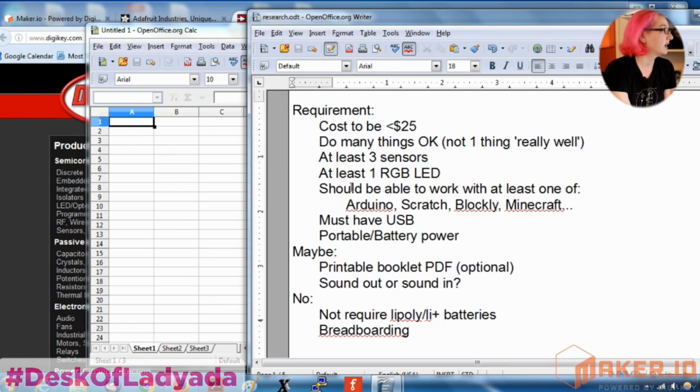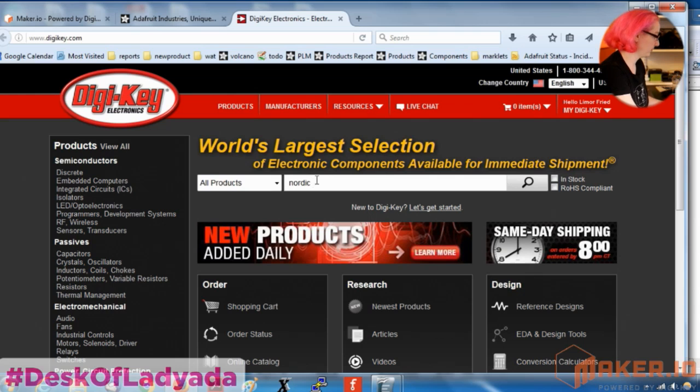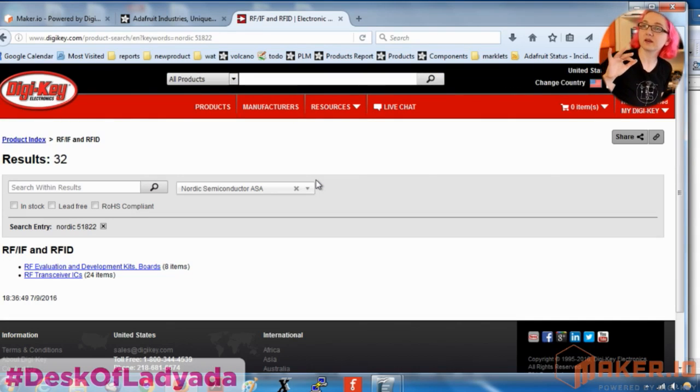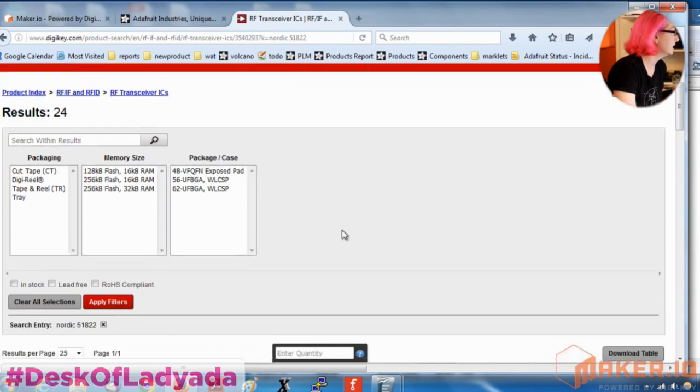So, during the research phase, I looked at some boards. Some boards had Bluetooth. So I would probably use a Nordic 51822 because it's a chip I know a lot. So we can look that up. Let's see, what does it take to add a Nordic 51822? This is a Bluetooth microcontroller that's a Cortex M0 with BLE built into it. There are also some chips from TI and CSR, but this is the chipset I know best.